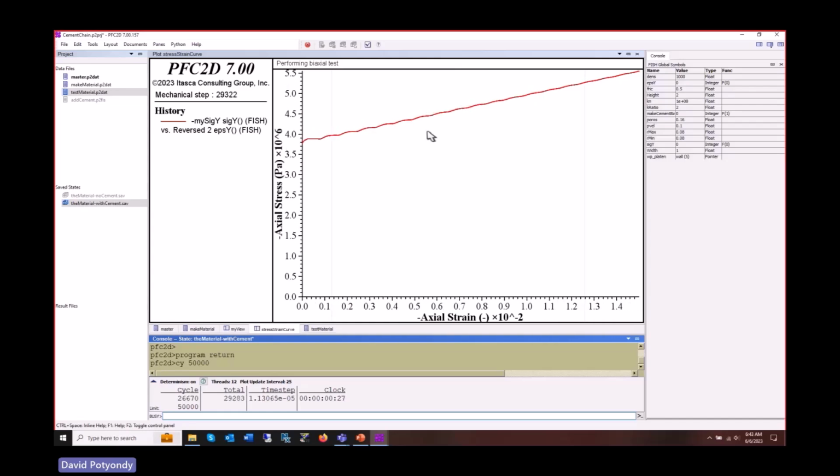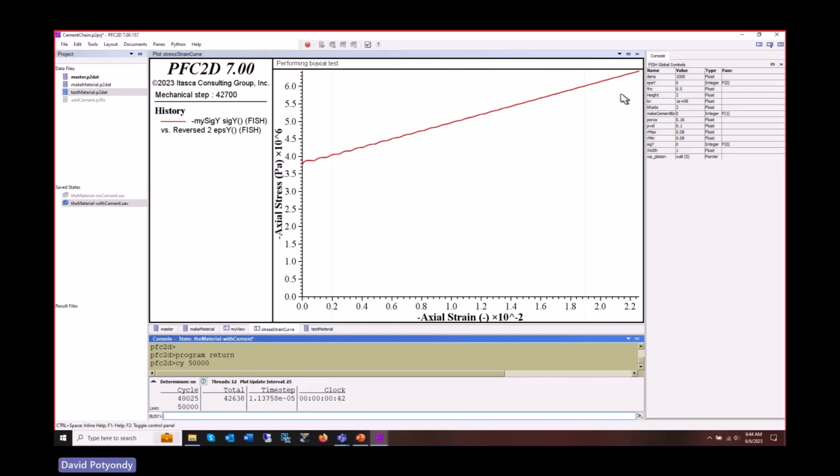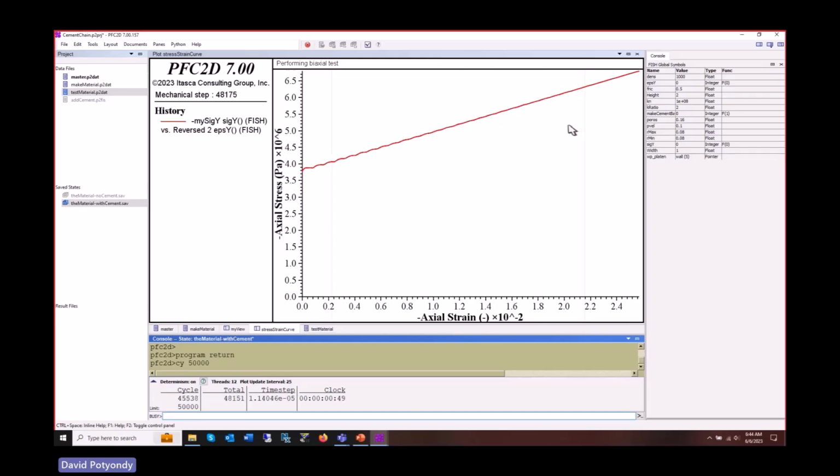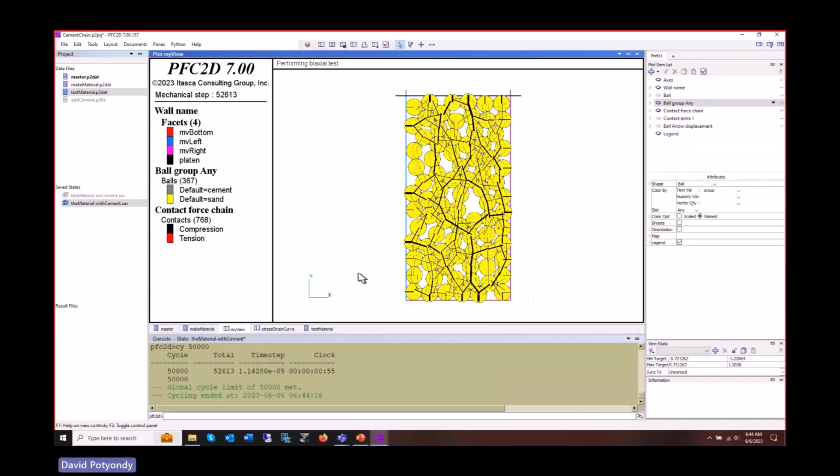We're going to find that this doesn't really have much of an effect unless this is super huge. This is just a minor thing. It's probably not affecting any breakages, and it's breakages that we care about. And so when we run our real tests, we're going to say, oh, look, it's not breaking, so it probably doesn't matter. And the overall stress strain curve is going to be the same for the different velocities unless we get really, really high. And notice how that ringing has damped out. And now we're getting a nice, clean, straight curve. And there we are. Okay.